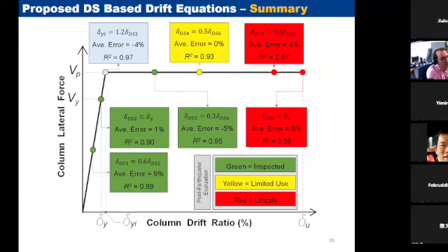You may call these damage states safe. So that's why we colored them green. The bridge can be opened right after the earthquake if you're at damage state 1, 2, 3, and you can basically green tag the bridge to be used by everyone. At damage state 4, which is yellow tagged, you have only 50% reserve capacity before it fails. So we are calling it, okay, be cautious. It's red tagged, only light traffic and first responders can use the bridge. And damage state 5 to 6 has limited to no safety factor built in before it fails. So if your inspector is reporting 5 or 6, that bridge has to be closed.